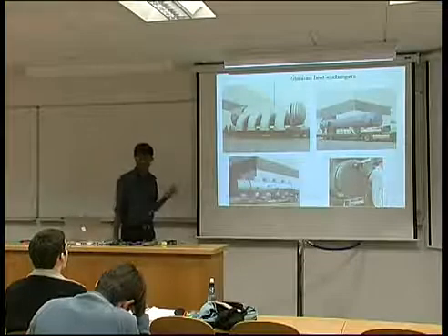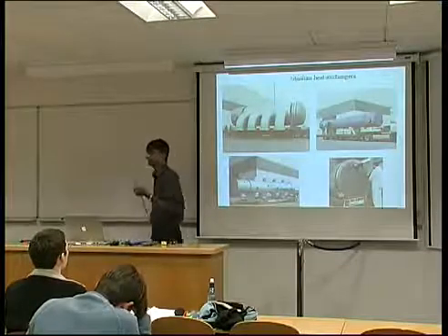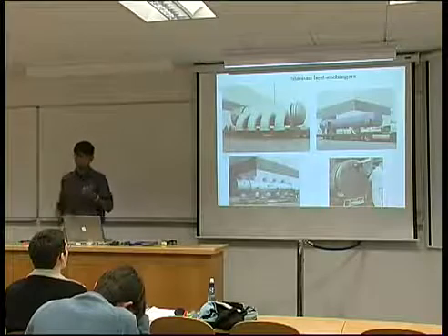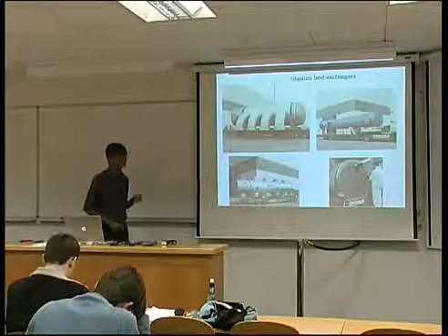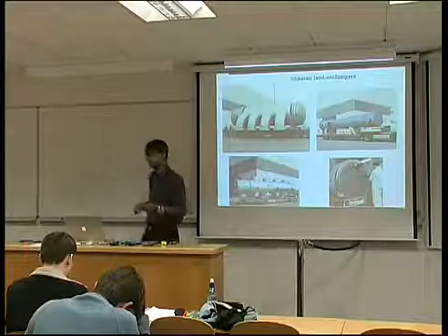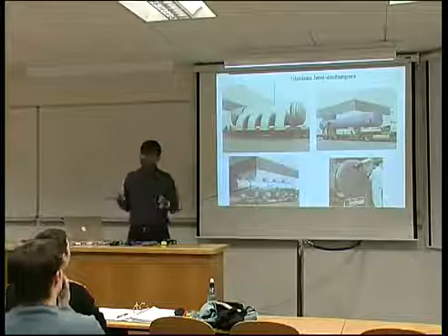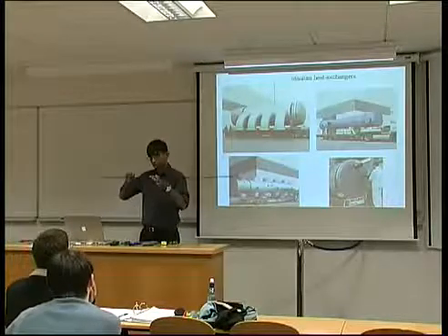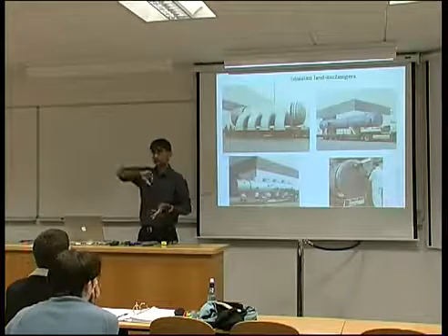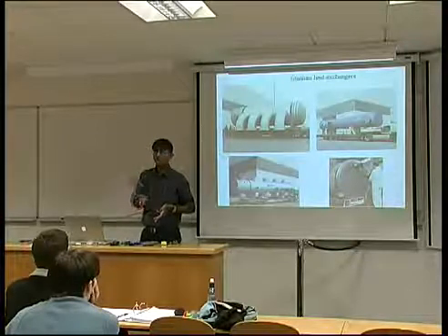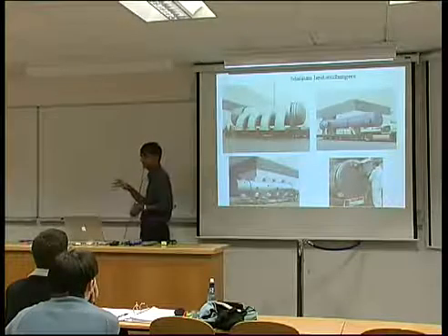Now, a lot of titanium is used in the chemicals industry because of its corrosion resistance, and I'll explain that in a bit more detail. But for example, these are reactor vessels, and they may not be completely made out of titanium. You might make them out of steel and then clad them with titanium so that the reaction actually happens in the titanium.